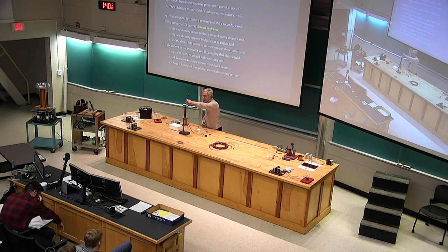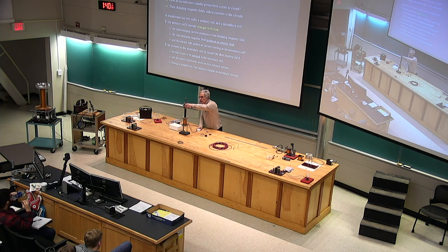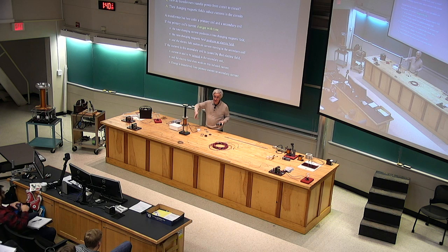When I bring this over here, I steal some of the energy from that magnetic field, and instead of going back to the power company, it goes into the second circuit. And how that's happening is because as the magnetic field is changing with time, it is creating an electric field, which pushes charges through that wire. The magnetic field is there right where the wires are, and it pushes charges around them. And just as a voltage drop creates an electric field to push charges through a wire, an electric field can itself create a voltage rise in a wire.